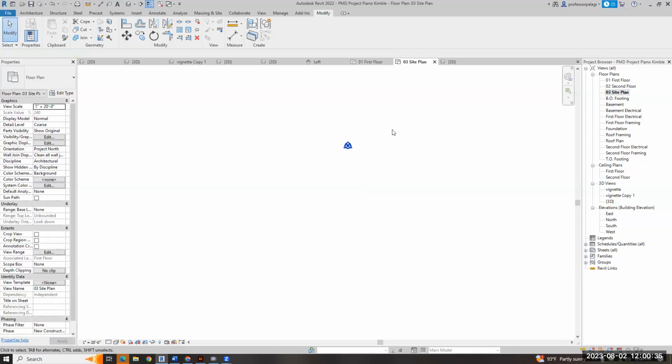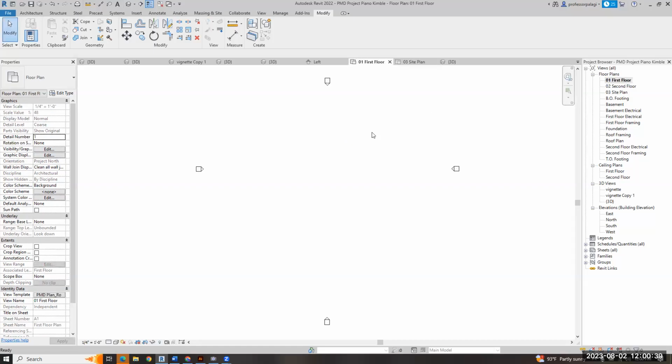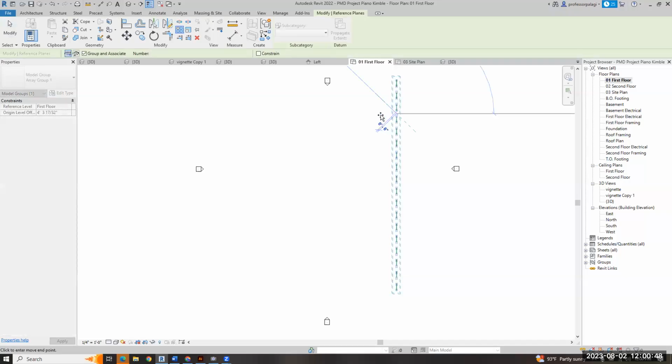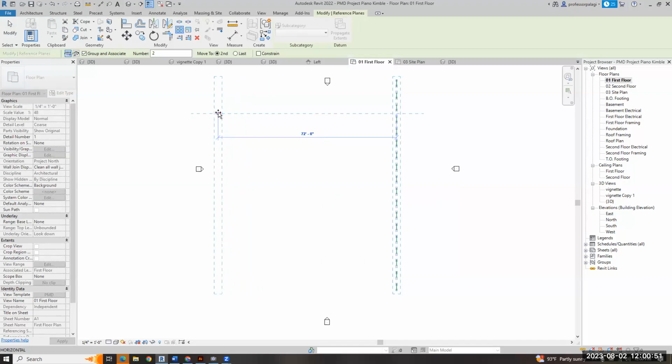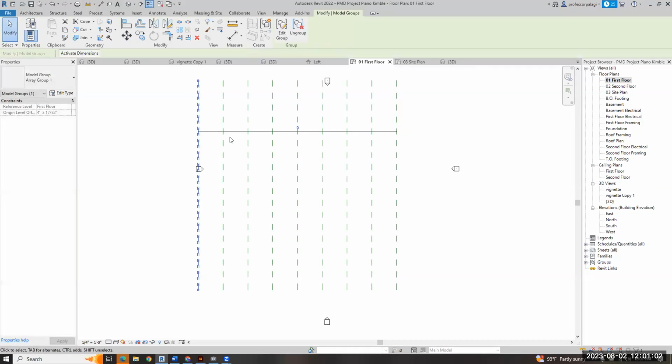All right, we're just going to start with that again, because that's killing me. Since I had it all set up, I drew a reference line. I arrayed it. I moved it over 80 feet. I said, go to last. I moved it over 80 feet. And then I said I wanted, in essence, 9 increments, which should give 10. Well, 10, 20, 30, 40, 50, 60, 70, 80, right? That was kind of how I did it.